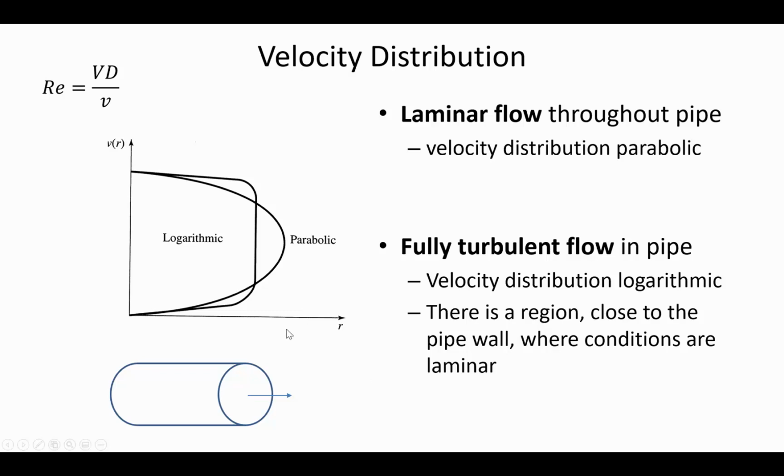This is what's causing the laminar sublayer: if you get close enough to the boundary of the pipe, the water really isn't moving that fast. And so velocity times diameter divided by kinematic viscosity, there's a lot of different velocities in the pipe. There's not just a single velocity in the pipe. We often calculate the average velocity just for convenience.